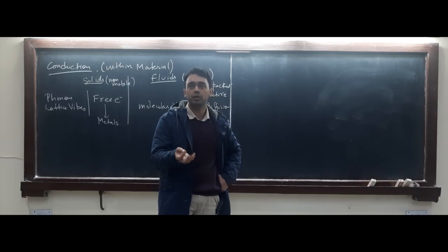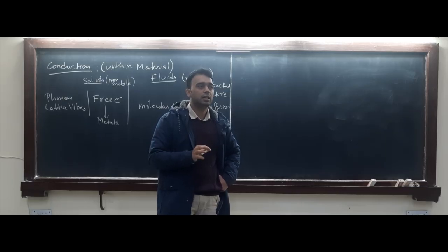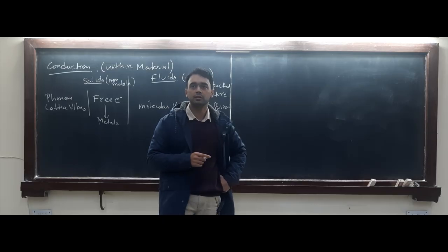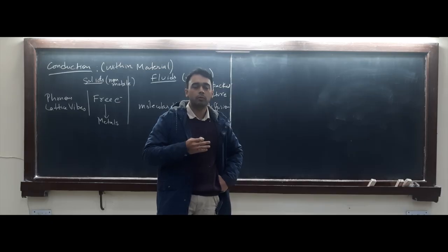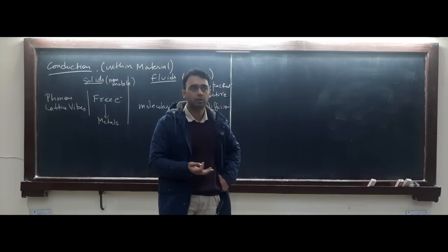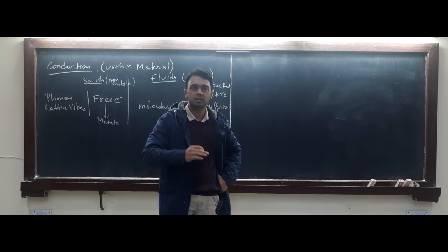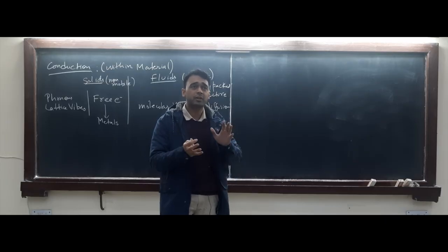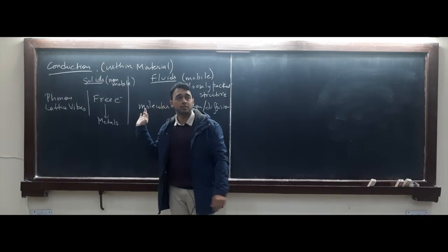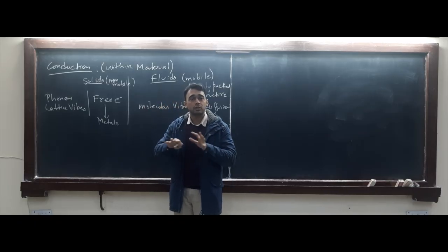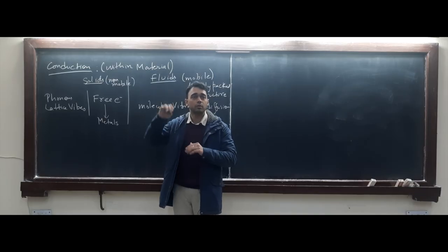And you should not confuse it with what you see in your teapot when you're making tea, and when you heat water, you see the water rising up and mixing and sloshing, right? That's not really conduction. That's something else that we'll talk about in a few minutes. But I'm talking about the instance when you start to make tea, you have a hotter surface at the bottom because the pan is getting hot, and a colder surface at the top. At those small instances where the temperature difference is not so large to trigger natural convection, you have that brief moment where purely conduction takes place. In that, the hot molecules will jiggle a bit more near the surface and the colder ones will remain on top.